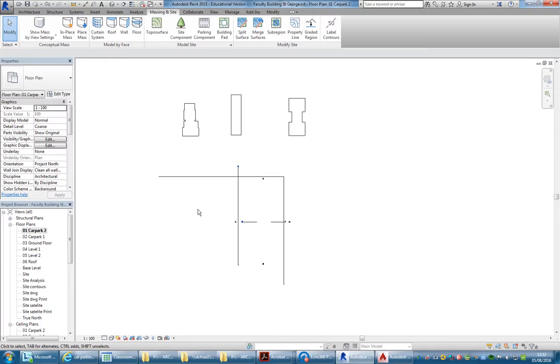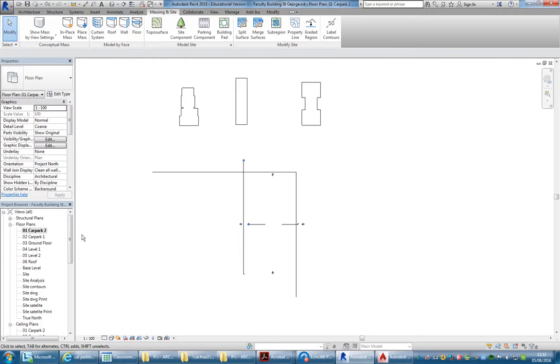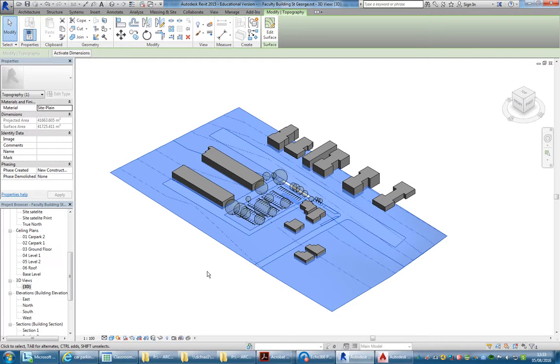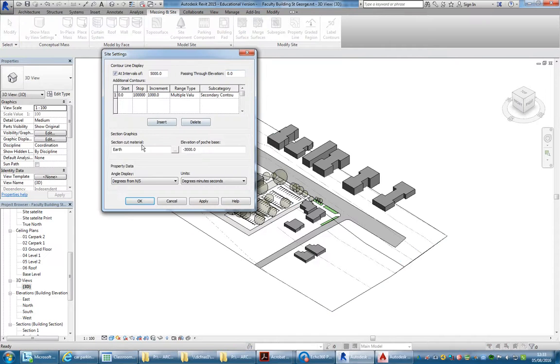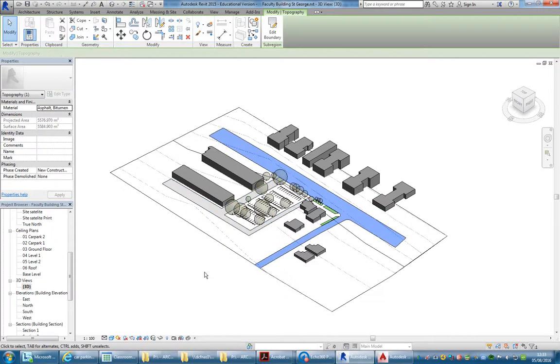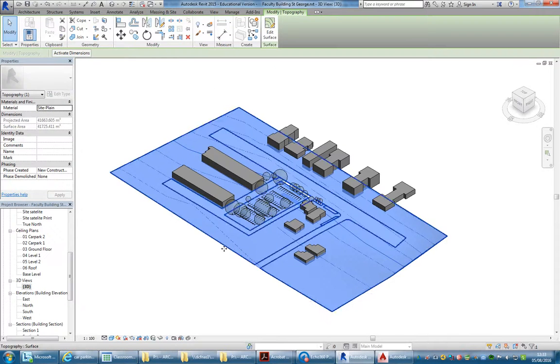So the next thing you might check is the visibility. Clicking on the light bulb there, we can see hidden objects, still not there. There's a bit of a secret thing in Revit that you need to know, that the topo surface as well has a material. So this option sets the way it shows in a section no matter what. But think about the topo surface, it's got its own material, and then each sub-region also has a material. They all show the same in section because of that site setting. But when you select the topo surface, you can of course set a material to it directly.